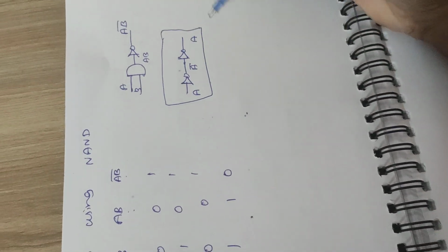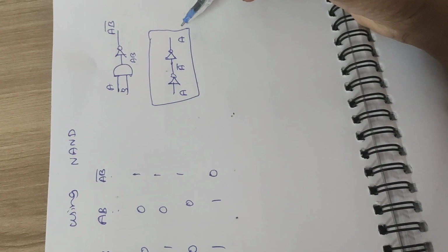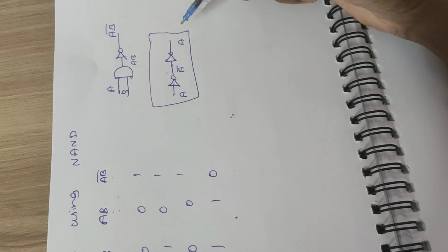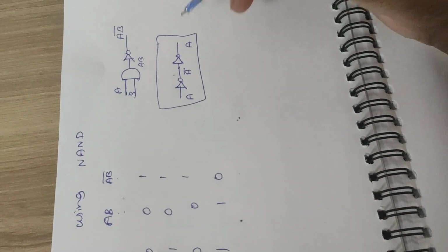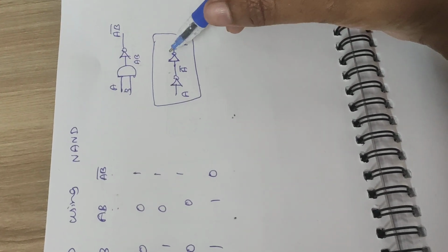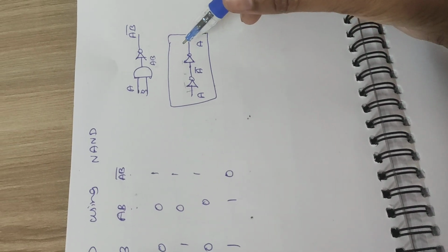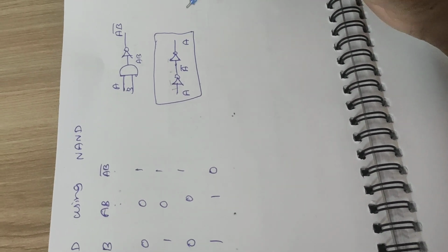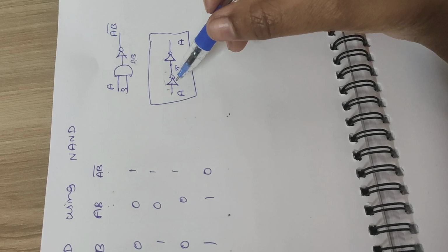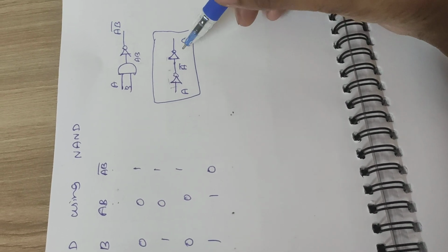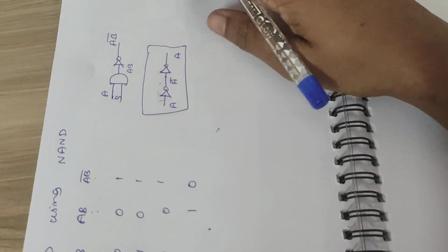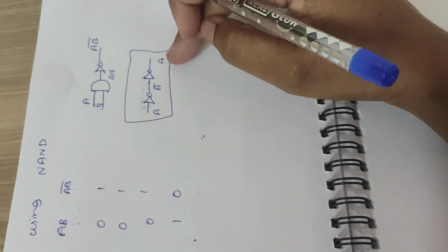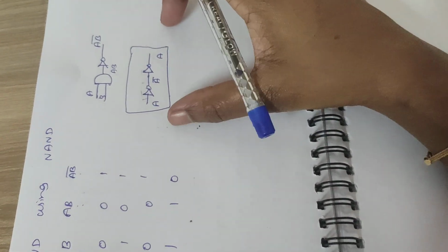If we have an even number of inverters in our path, it will be the buffer only. Two inverters we have added, so it will just give us the same input we have given, but with different directions and all. But that is a different concept. We can go into depth on that sometime later. Back-to-back inverters will also be there in real design, so we will talk about that later. Generally, logically it will give the functionality of the buffer. So if we give input A here, the output also you will be getting A only. So this concept you remember.